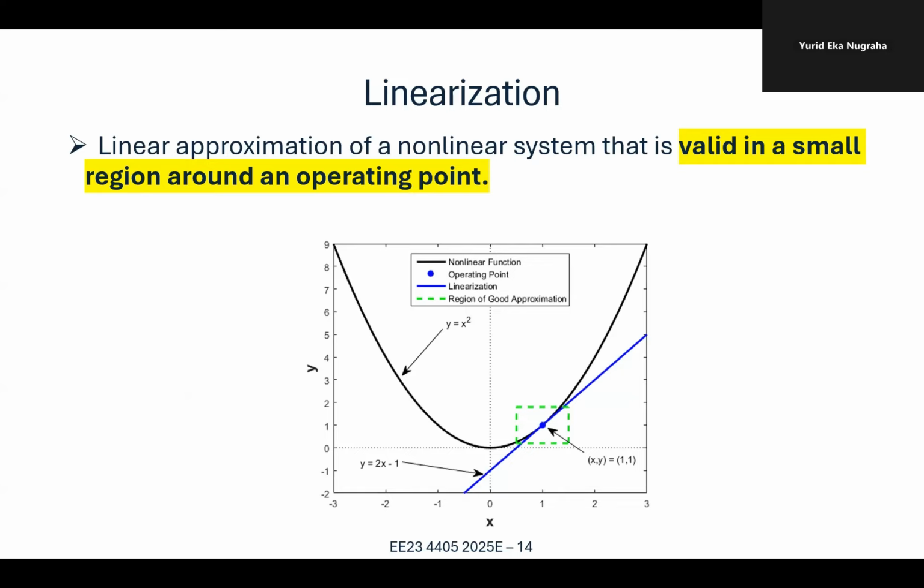If we are talking about, let's say, the drone, and we want to perform automatic takeoff or automatic landing, then the linearization point here is for the angle to be, let's say, 0, because we expect them to operate mostly at angle 0.